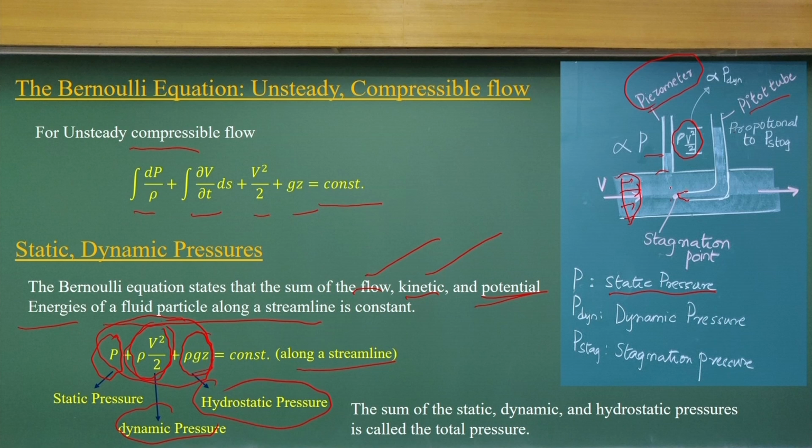When you have a pipe flow, you can measure the pressure using the piezometer. Using the pitot tube, where you insert a tube with a sharp point to raise the fluid inside the tube, you measure both the dynamic and static pressures. Since we know the static pressure, you can just compute the dynamic pressure. The stagnation pressure is the sum of static pressure and dynamic pressure.